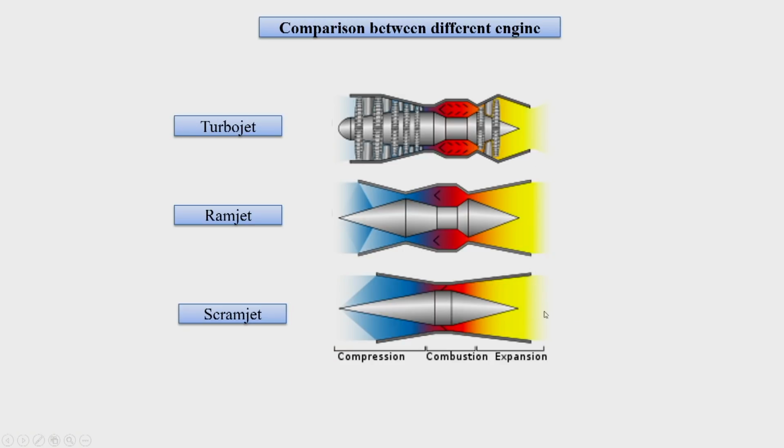So, here we practically are going for higher Mach numbers. Jet velocities are becoming higher and higher in the case of ramjet and then further higher in the case of scramjet engine. So, this is the difference between different engines. As we have seen, propulsive efficiency decreases if the ratio Cj by Ca is increasing, or if Cj minus Ca is increasing.